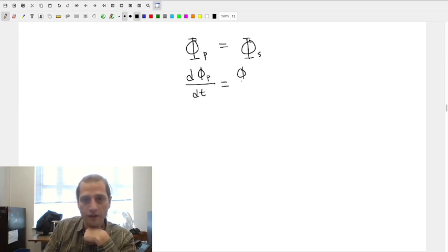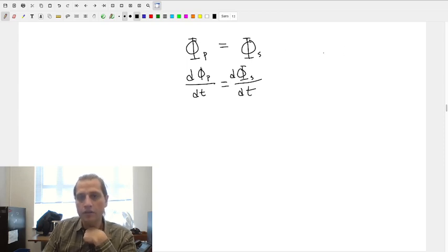This is the magnetic flux, dΦ/dt. Okay, now we're going to use Faraday's law, which says that the voltage is related to N times dΦ/dt, and it's going to be a minus, but it's always changing direction, so we're going to be a little bit sloppy with the phases here. Okay, so this is Faraday's law.